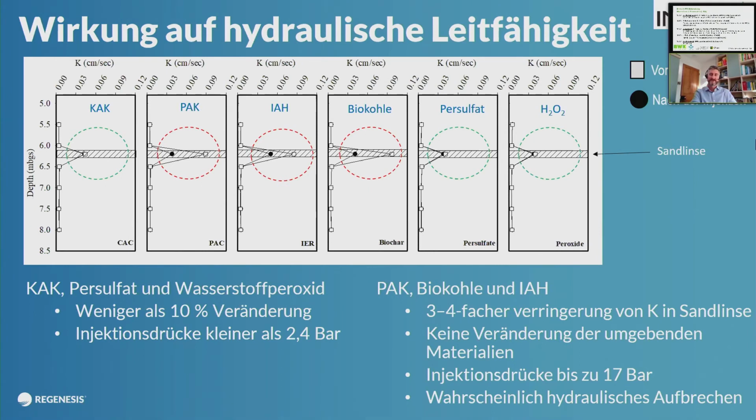With the larger particle size of the other materials, they've had to fracture those in. It looks like most of it has forced its way into this sand lens and started to block that sand lens, so that hydraulic conductivity has been affected by the application.